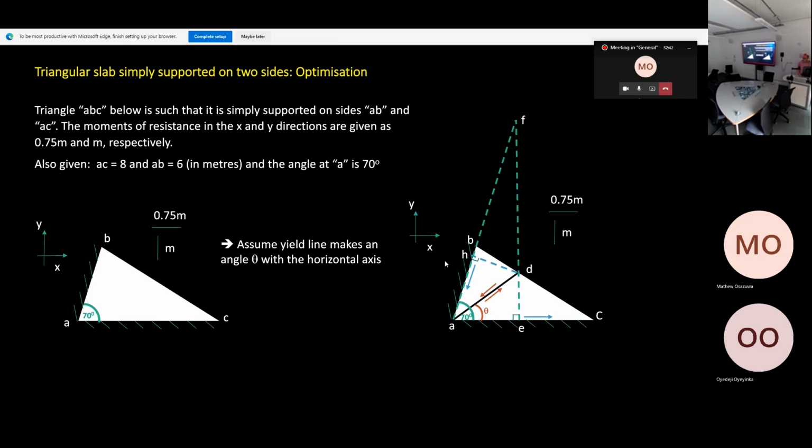Okay, now the rotation vectors. Do you agree with the direction of this vector here for the rotation? Using the left hand, the rotation is going from you into the screen. So that's the direction of the vector. The slab rotates like this. This is the left hand, and this is the direction of the rotation vector there. So we've got everything here now that we need to start the internal and the external work.